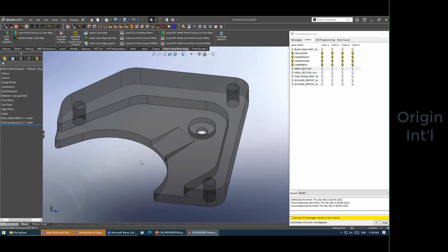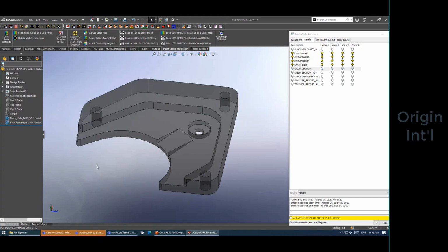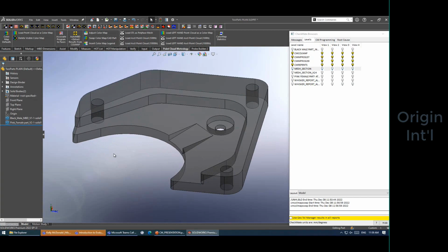Well, that's the problem, Jim. That's what this is all about: when you start dealing with multiple components of the same assembly, if you go and look at the print or the MBD, they all have their own A, B, and C, which would all be different, right? So you have to be able to handle that in CheckMate, having multiple segments, all with A, B, and C datums, but they're all different features. Right, and that automatically took care of the repeat issue with the P in front of it, right?